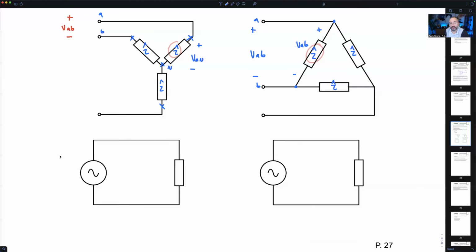If you were in circuit analysis class last week, you know this like the back of your hand. We did 6, 7, 8 examples of this. So here's our single-phase equivalent circuit for the Y and the delta. What voltage goes right here? This is always my line voltage divided by the square root of 3. We can call this the line-to-neutral voltage to avoid any confusion.